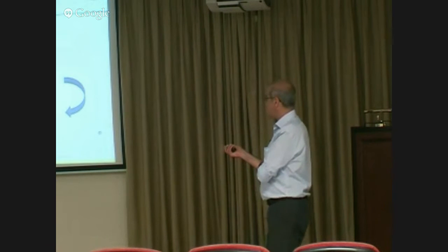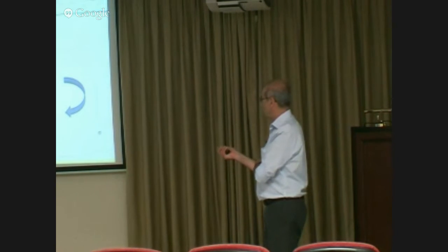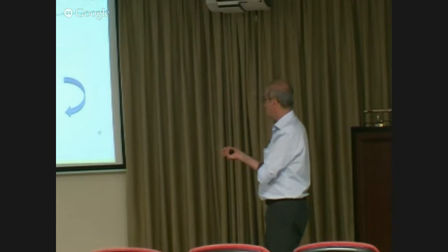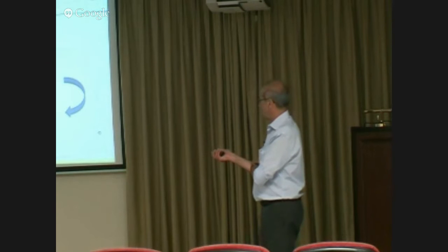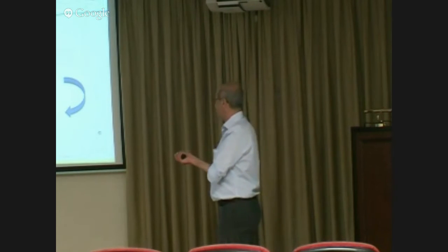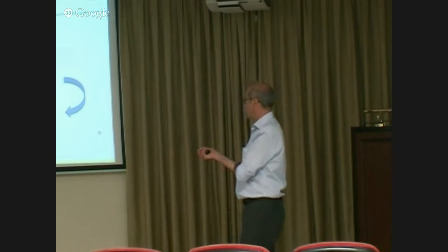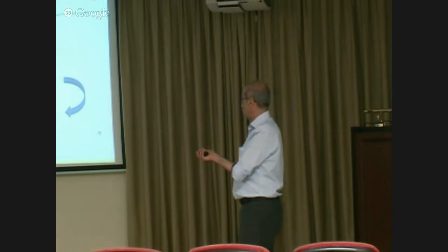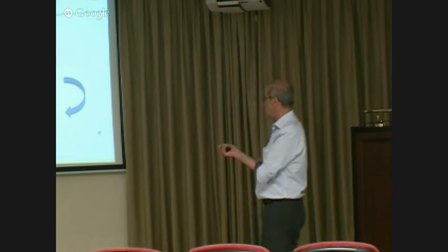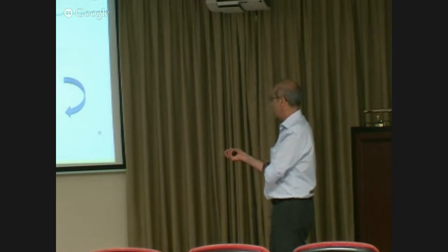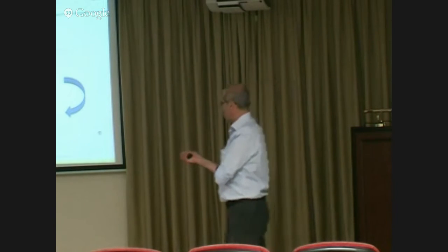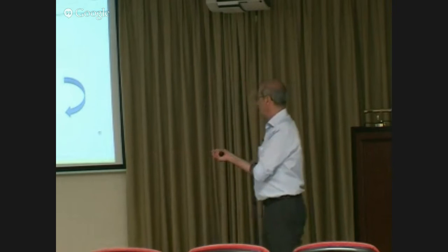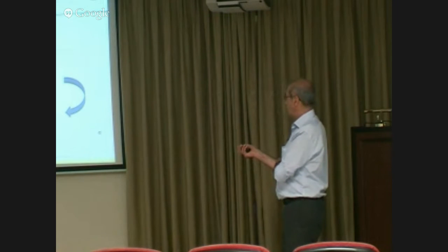You can take this and replace it by an equivalent picture where this is still connected, but by adding appropriate injections on each side, equal to this flow, you can eliminate that flow and make this picture look exactly like that picture in terms of everything, voltages, flows, and so forth, other than these artificially inserted flows.